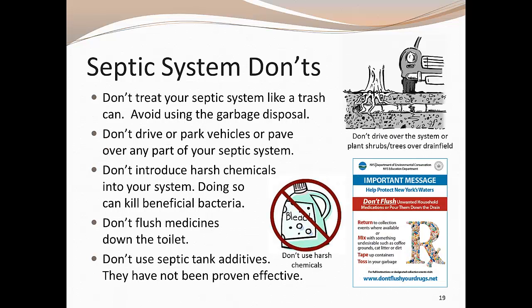Here are things to avoid when trying to maintain your septic system. Don't treat your septic system like a trash can. Avoid introducing finer floating solids and material that's difficult to digest. Avoid using a garbage disposal. Don't drive or park vehicles on any part of your septic system. Doing so can compact the soil treatment area and damage pipes or tank or other septic system components. Don't introduce harsh chemicals into your system, which can kill needed bacteria.